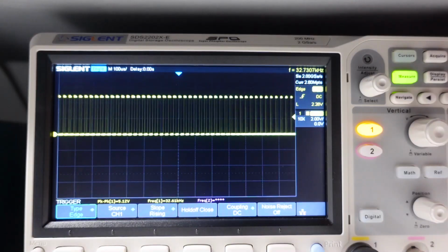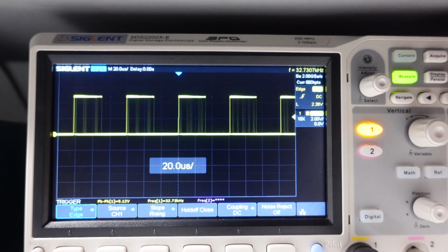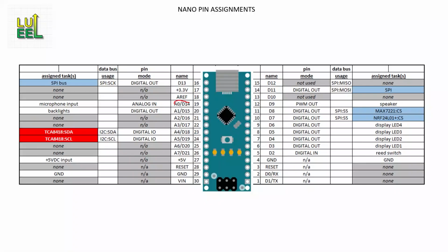So I set up his example code, and right away I got the Nano to output a 32 kHz square wave using timer number 1 that was pulse width modulated to replicate a 440 Hz sine wave. Nice! So the next step in software is to take the digital signal input from pin A0 and push it out as a PWM output on pin 9.